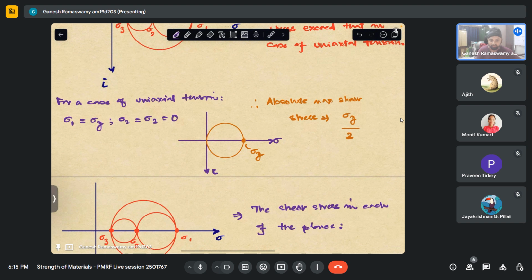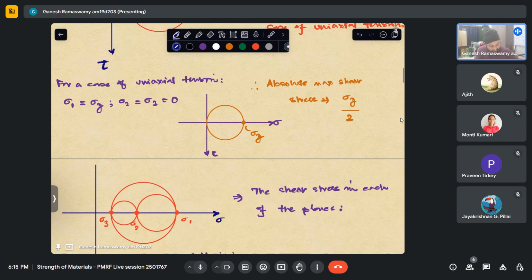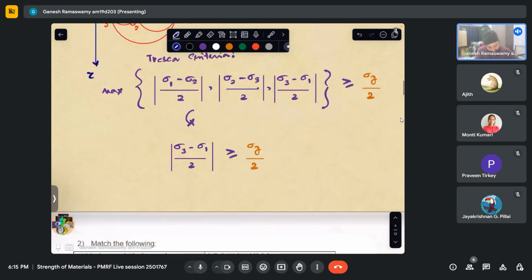So along similar lines, we have actually seen the maximum shear stress here. Another theory relates to the octahedral shear stress, which is called the von Mises theory. So I will just be stating the formula here, but the derivation can be easily derived, and it has also been done in the lecture, so I'll avoid that here. Anyway, we will be seeing as we go about how to apply these.